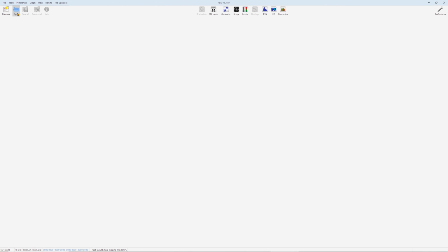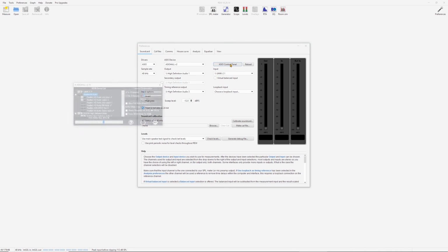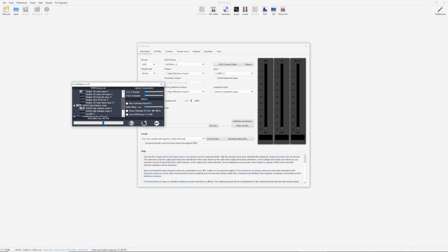I will not do all the measurements. There are 10 speakers. Each location I measured to the left of the central position, right of the central position, and central position. Only 3 locations. Even that is like 30 measurements. But I will show you how to measure the height speakers and how to switch between REW-generated files versus its own generated sweeps. Initially, your ASIO control should be on your receiver here, okay?